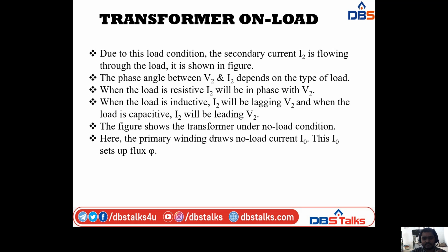When the load is resistive, I2 will be in phase with V2. When the load is inductive, I2 will be lagging V2. And when the load is capacitive, I2 will be leading V2.